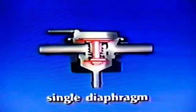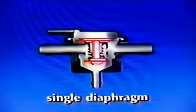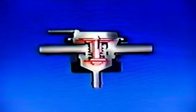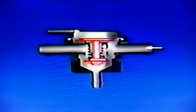The first and more simple purge system uses a single diaphragm operated by manifold vacuum. Here's a cutaway drawing of the valve. This type has a hose from the carb bowl to the control valve and onto the canister. When manifold vacuum is applied to the diaphragm, it pulls the purge valve up and shuts the purge off, preventing the carburetor from venting to the canister. It's only when you open the carburetor and apply ported vacuum or purge vacuum that you can succeed in purging the canister.